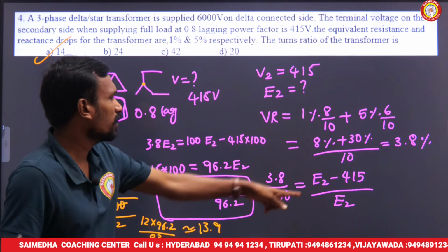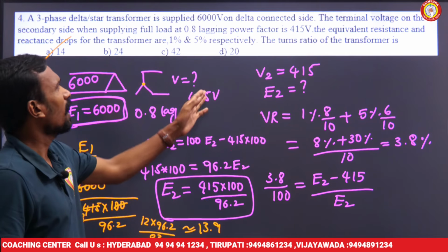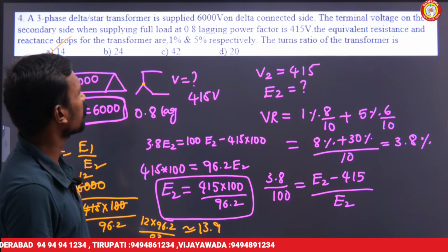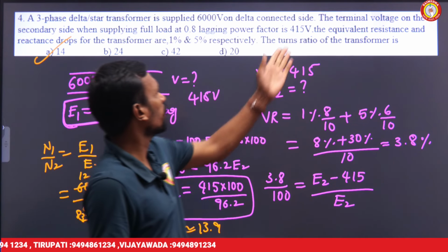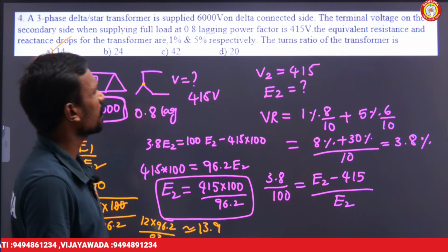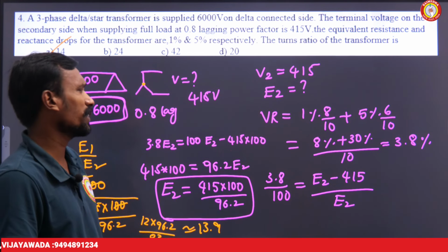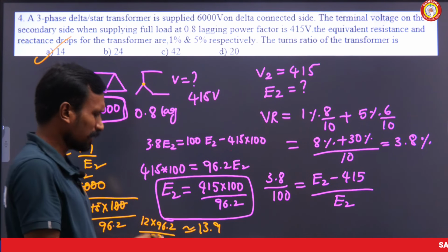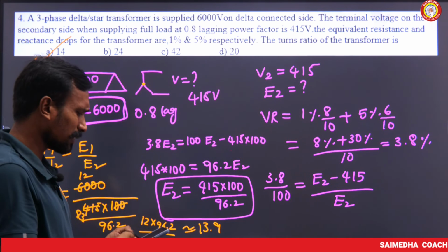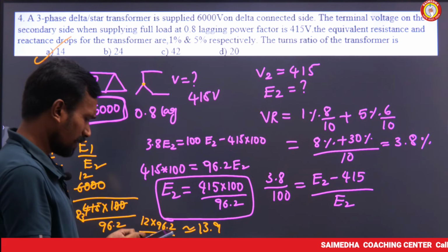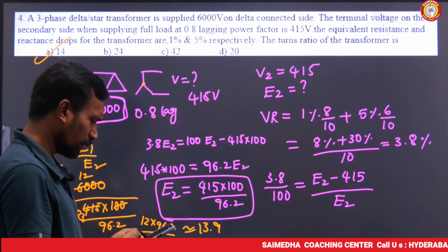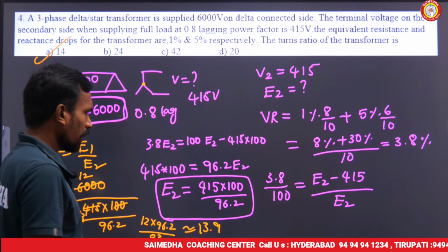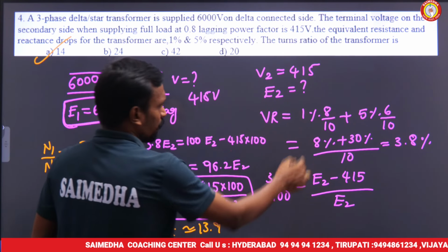Directly. So this is a phase voltage, and of course the 415 volts they given, we will take as a phase voltage. If it is line voltage, we need to change again. If 415 volts is a line voltage, then what will be the answer, sir? If it is a line voltage, just calculate 415 by root 3, which is nothing but 240. Let's take 240.